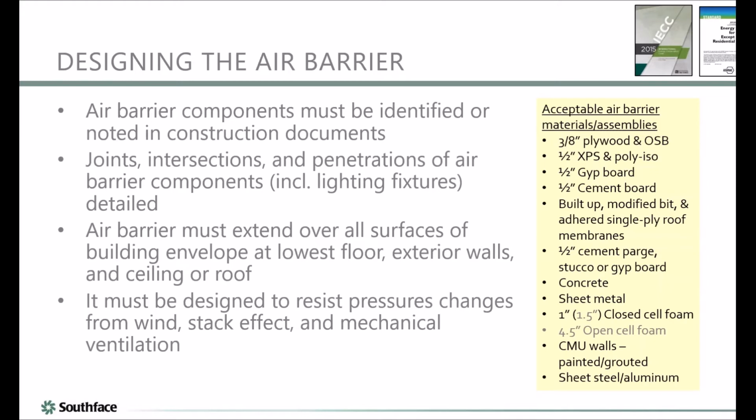But they list materials which they deem essentially viable or worthy as an air barrier, exactly. Which is somewhat naive, because our experience is, yeah, it's true, and probably you're going to be building with one of these many materials that are listed here, but that's not where the failure occurs. The leakage doesn't occur in the middle of a piece of OSB. No. It occurs at the penetration or at the seams, that kind of stuff.